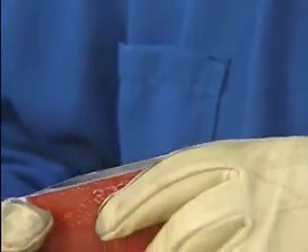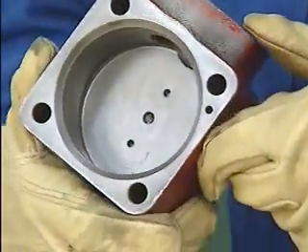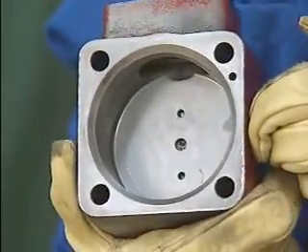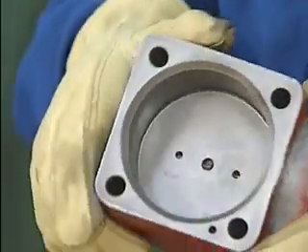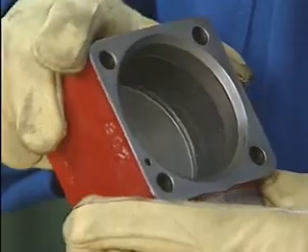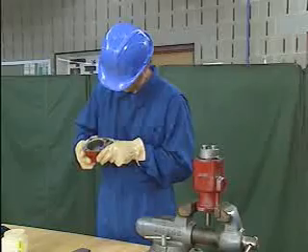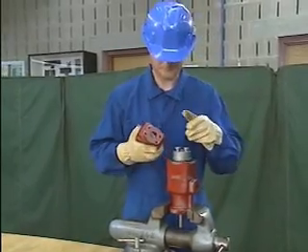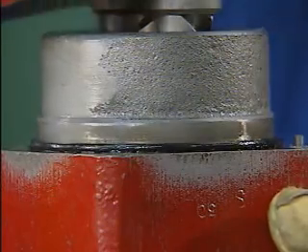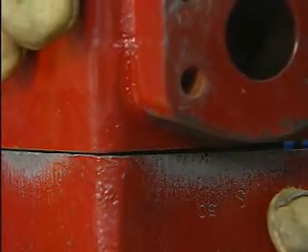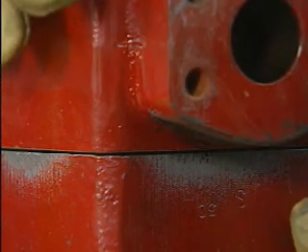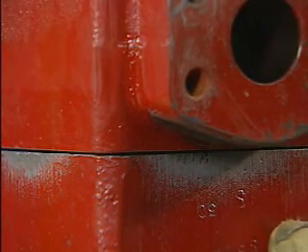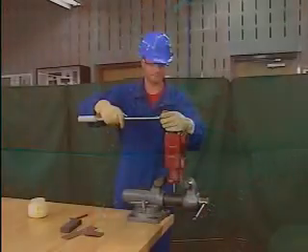Like many O-ring applications, the opposing or mating flange has a special fit designed to help compress the O-ring into position. On this application, the mating flange has a beveled edge that contacts the O-ring when the two flanges are bolted together. The angle of this beveled edge compresses the O-ring evenly against the vertical surface of the sleeve and the horizontal face of the flange, forming a proper seal.